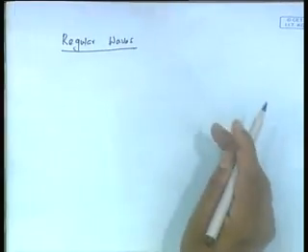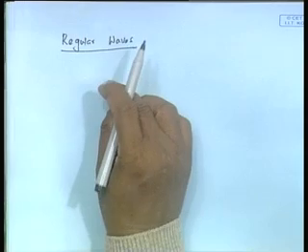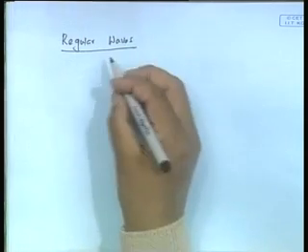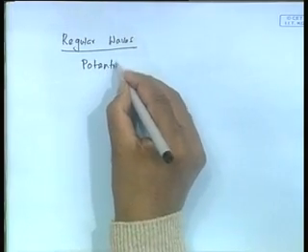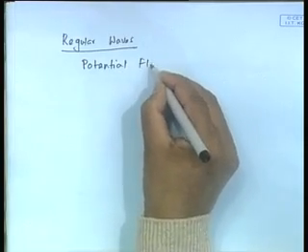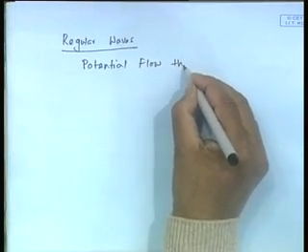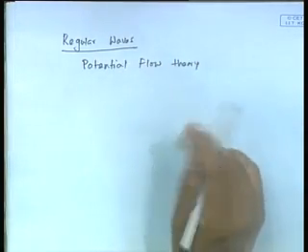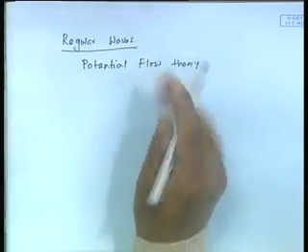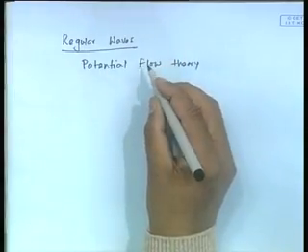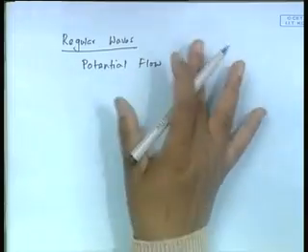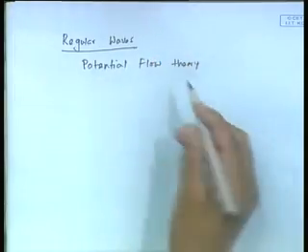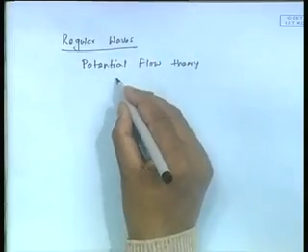We know theoretically that regular waves are studied based on potential theory, which means that the fluid is assumed inviscid and the flow is assumed irrotational. The fluid is also assumed homogeneous and incompressible.